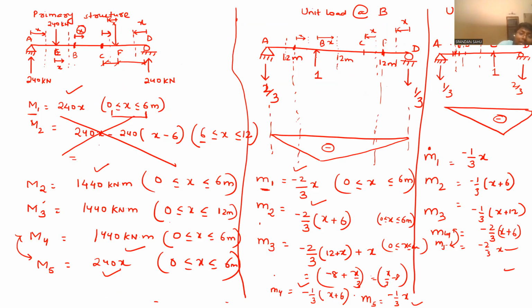When you apply this load, you have to calculate displacement at this point B due to unit load at that point. So you apply 1 unit load, there will be some displacement. Due to that 1 unit, the beam will bend. Due to that bending, those equations will be developed: M1, M2, M3, M4. Similarly, when load at C equals 1, you will get M1, M2, M3, M4 respectively.